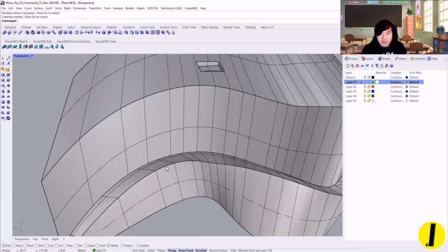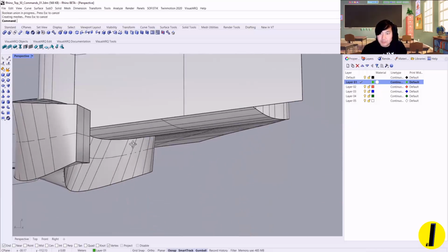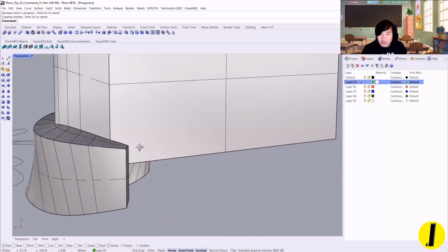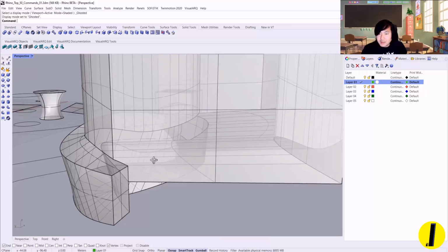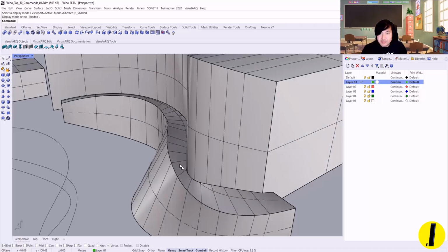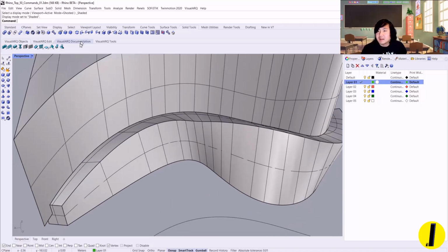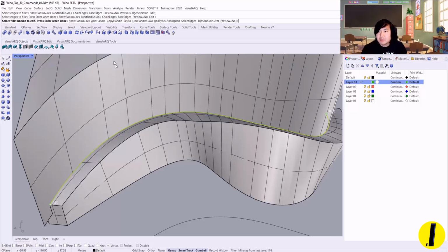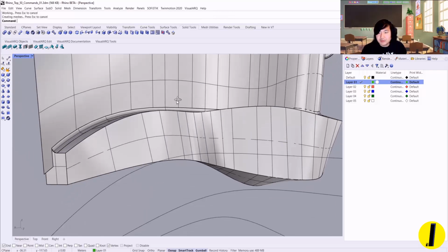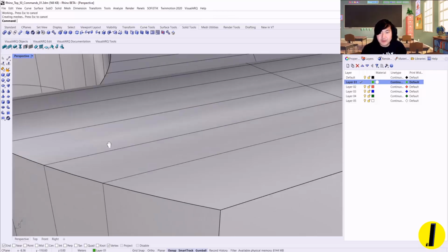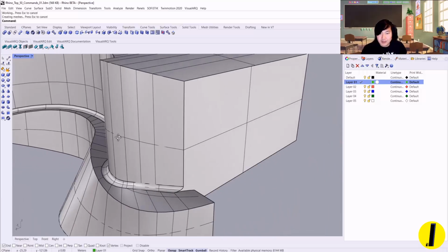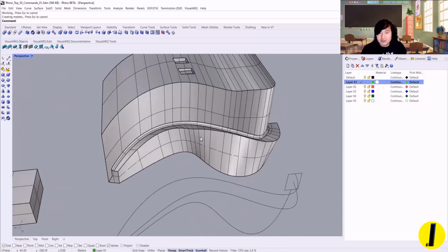So we have now this as one solid, where it's not just edges. As you can see here, we can fillet the geometry. Probably I'll give a bigger radius, 1. Let's see if it works. As you can see, it's beautiful. It works perfectly with fillet edges.